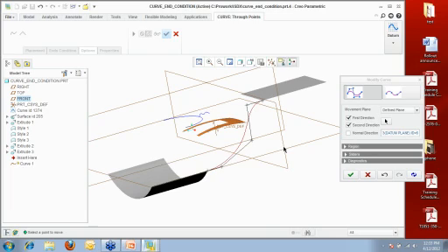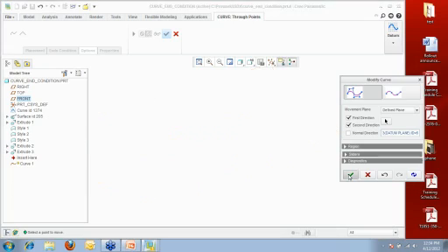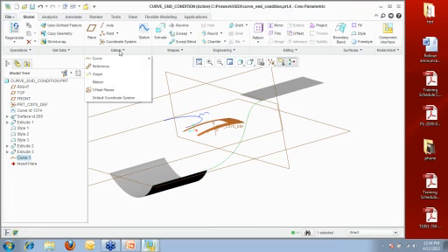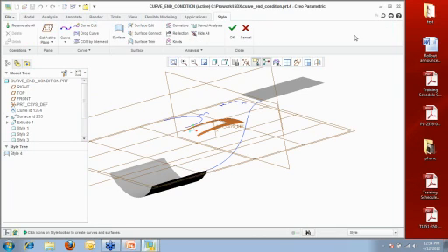And so using not only ISDX tools and some of the button clicks that you guys can't really see, I can talk about a little bit, but also the four views that we have, it makes it a lot easier just to tweak and move and kind of define curves. So what I get for tangency going in and going out into the curve, it is what it is. I don't have the ability to kind of tweak this. I can add in points and kind of move it, but I don't have a real robust way to alter this. And so here are the differences between just the out-of-the-box, come along with Pro E, curve datums, and then also now the style tool.